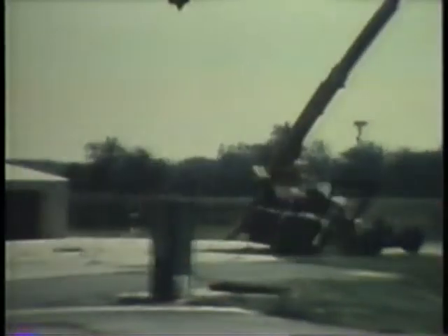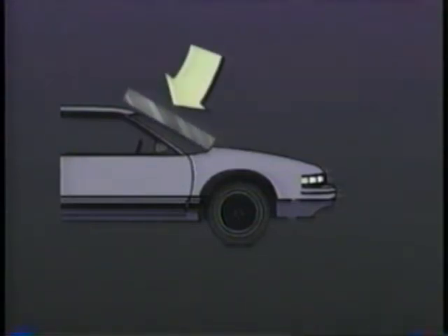To further protect the occupants in rollover accidents, passenger car roofs are tested for crush resistance. A rigid, unyielding block with its lower surface formed as a flat rectangle, 30 inches by 72 inches, is applied to either side of the forward edge of the roof. When a force, the lesser of 1.5 times the vehicle's weight, or 5,000 pounds, is applied, the roof must not move inward more than 5 inches.